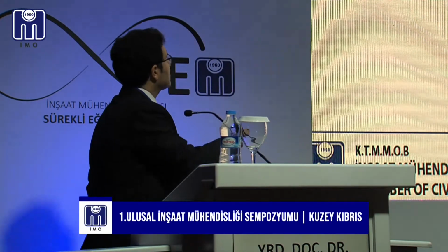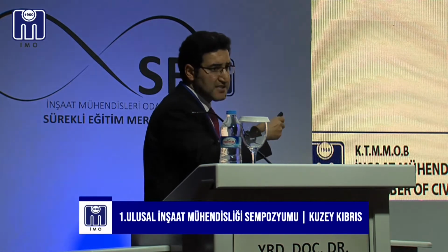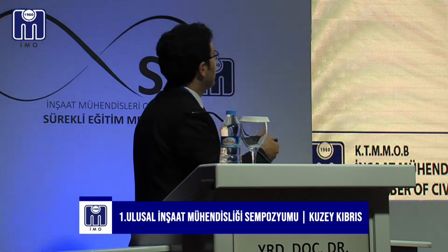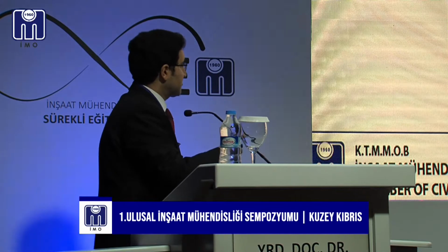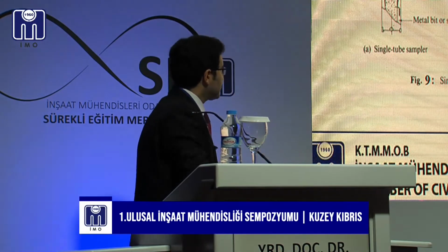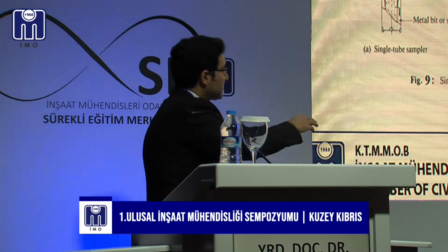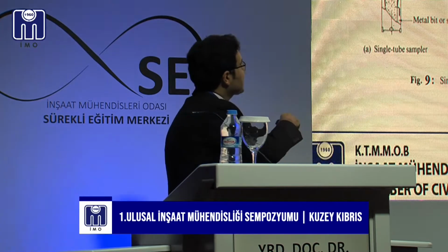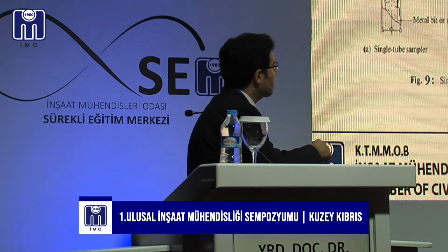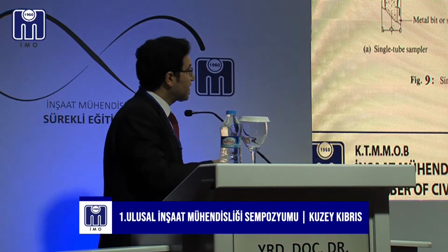First, we consider block sampling. Why do I use this figure? It is very easy to handle in the sand and easy to get an undisturbed sample by this method. For other undisturbed soil sampling methods, we use the single tube, Denison and triple tube samplers, as well as the advanced gel push sampler developed by Kiso-Jiban company in Japan.